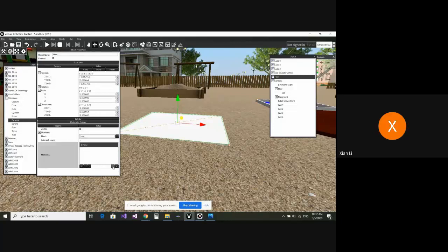So you just press the minus button, get rid of it, and then press the plus button. So add another template where you can add your material and make all the changes. In that way, anyone who uses that shared material will stay the way it is.